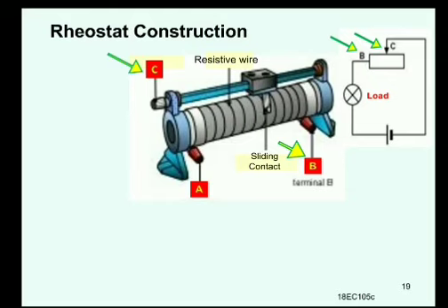And if you look at the difference between a normal resistor and this rheostat, it is the size. The moment you look at it, it gives an impression that it is a bulky thing. So this is where the difference lies. Rheostats are mainly used for large current variations or control in applications. So this is what the construction looks like, and let us see a few more types.